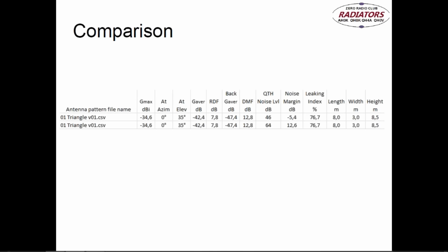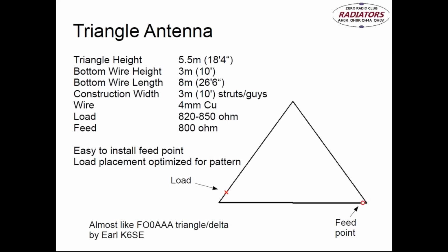Well, if we look at an 80 meter beverage or a 160 meter beverage, there's an 80 meter or 160 meter wire conductor. If we look at this kind of antenna, that's like 8 meters here, 5.5, 6 meters vertical. This is going to receive much less energy from any lightning. So any kind of thunder is less of a problem to this. But if you have your coax going to your receiver and it's connected to the receiver, then any nearby lightning is going to burn your receiver front end pretty surely. So this is not a thunder protector, but it receives much less energy from that kind of electrical or electromagnetic fields on certain occasions.